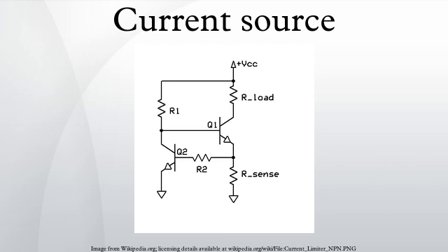This causes the VBE drop to fall to, say, 0.2 V. Now the voltage across the emitter resistor is 0.8 V, twice what it was before the warm-up. This means that the collector current is now twice the design value. This is an extreme example of course, but serves to illustrate the issue.